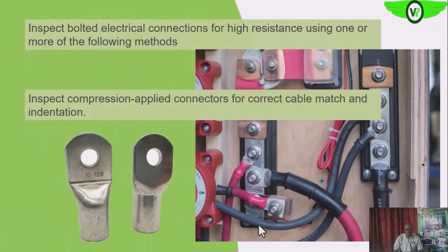So next, what you need to do, you look at these terminal lugs, okay? Be sure that the actual size is selected for the cable.